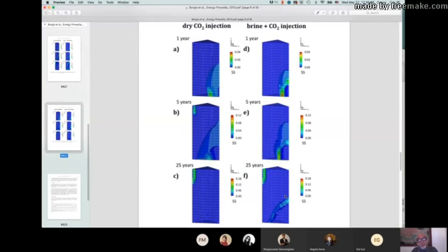The only problem of using this is that the CO2 gas is so rich, even if just in traces, is rich of mercury. And therefore you expect all your iron and steel piping to be contaminated with mercury as an amalgam at the end of your production.